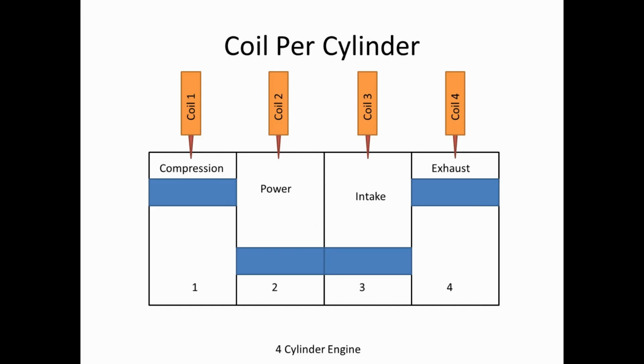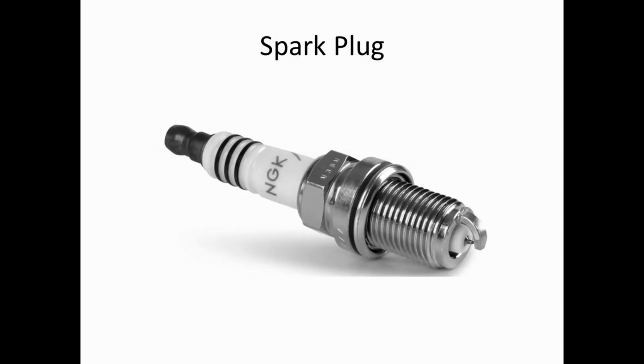So this is basically the way it works. We got our 4-cylinder engine cutaway, but now each cylinder has its own coil, and the coils are controlled specifically by the PCM, both the timing and the order.